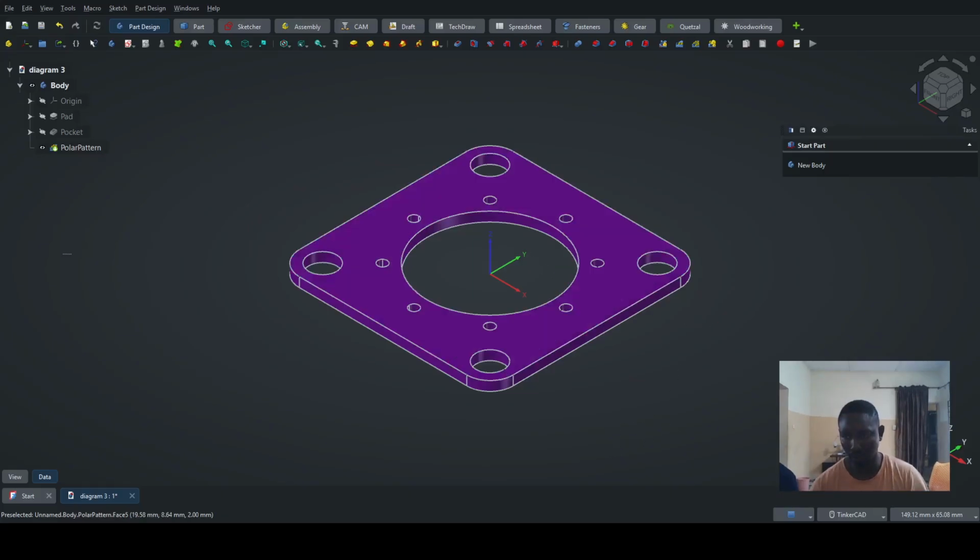So also, if you are using a mouse, I advise you to come down here. Here, you should click on this and choose FreeCAD. You choose FreeCAD as your navigation option. Or if you are using the touchpad, it may be beneficial to you to use this option. But I would prefer you use FreeCAD because that is what I use.